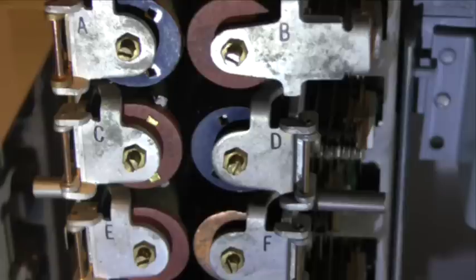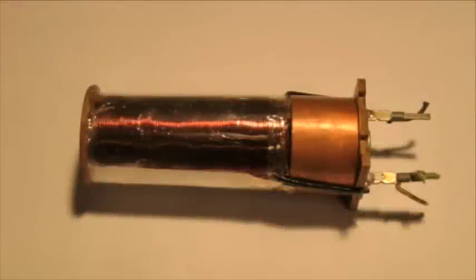The slow release feature is accomplished by the addition of a delaying device, which can be a copper slug mounted around the heel of the iron core, which is what the C relay uses, a solid metallic sleeve surrounding the iron core, which is what the B relay uses, or a secondary non-inductive shunt winding, which is what the E relay uses. The only visible delaying device that I have to show is the copper slug.